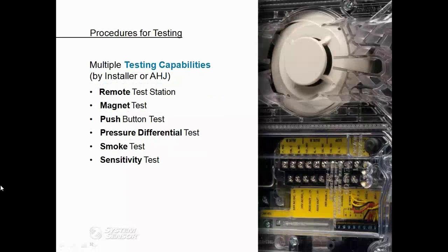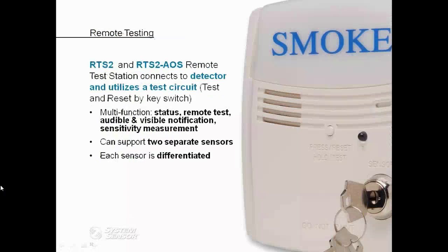One of the best ways, as we've mentioned many times already, for testing a duct smoke detector is through differential pressure testing. This test verifies that the detector will properly respond to smoke by ensuring there is proper airflow across the sampling and exhaust tube. This is done through the use of a manometer. The final way of testing is to apply smoke directly to the head.